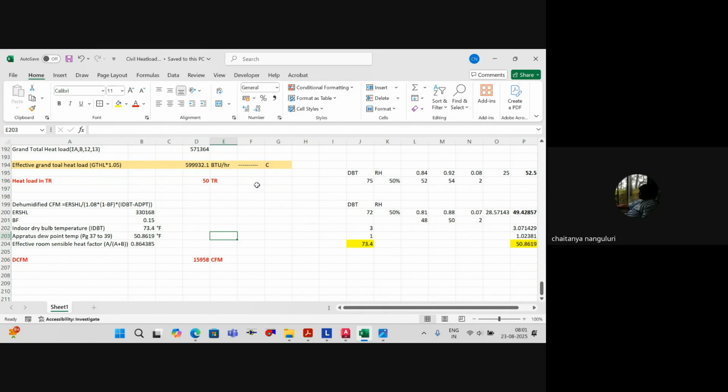No, there again you have to calculate according to the inlet moisture content. It's nothing related to your heat rate. The last two steps we got now, the total heat and how much CFM is required for that heat, you can use directly this formula. In fact, Q is equal to 1.08 into delta T, that particular equation you can use. The particular heat, how much CFM is required, that formula you can use. If you know what heat you have to extract, you can use that formula.